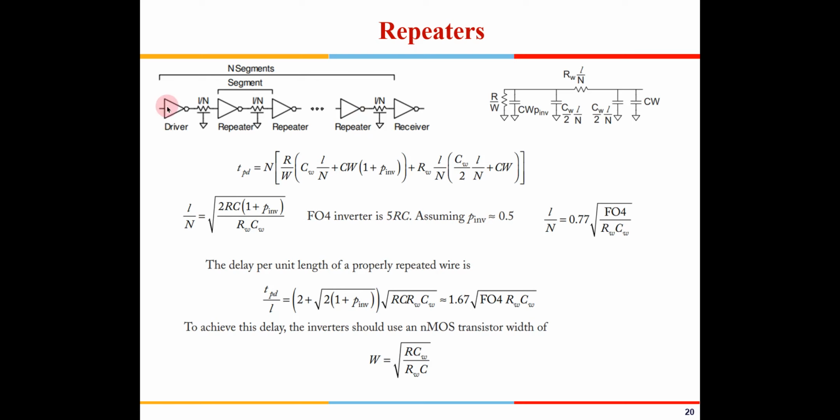What happens is, suppose you have a single wire. It is taking a total of 10 nanoseconds to rise to half the VDD. Now suppose I have put two inverters in between. The first inverter is in between, so within 2 nanoseconds it will reach the switching threshold of that inverter, and that will trigger an output swing. Again that wire length is short, so that will again trigger, because the moment it reaches the inverter threshold, that will trigger a change in the output. So obviously power will be more, but it will decrease the propagation delay. That is how the repeaters work.